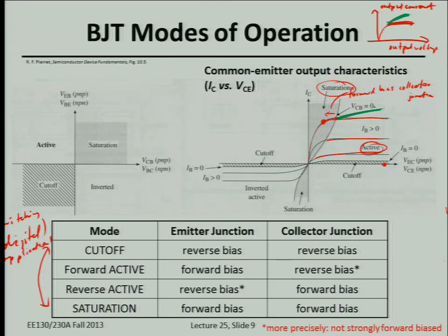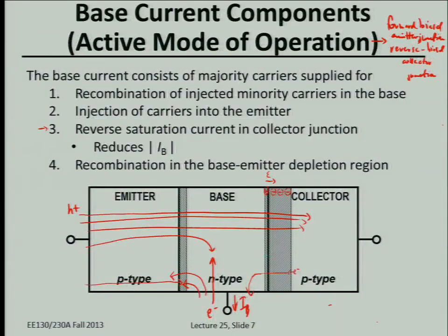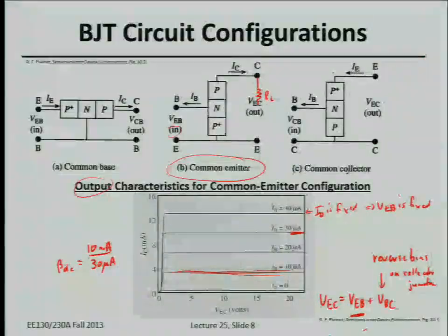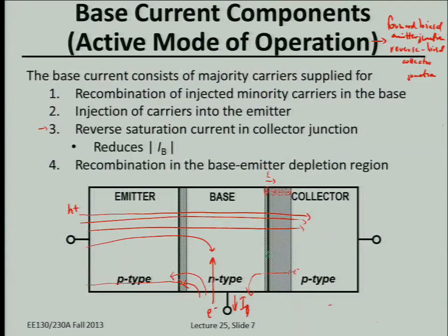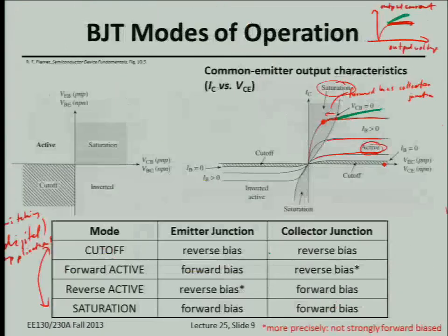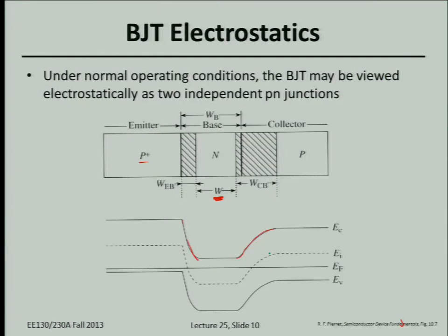And that slope, okay, so as you go to higher and higher output voltage, what you're doing is you're reverse biasing your collector junction more and more. If you reverse bias your collector junction more and more, what are you doing to the width of this depletion region? You're increasing it. So you're widening the depletion region while you increase the output voltage. And if the base width is getting narrower, the diffusion gradient is getting steeper. So this is called base width modulation, this quasi-neutral base width modulation.